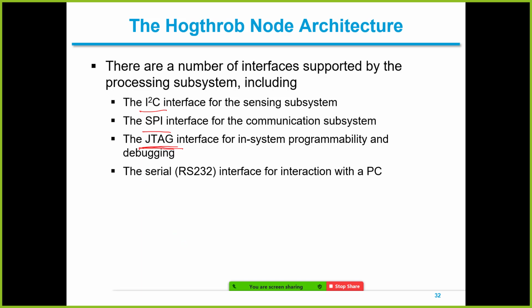So we achieve that through this JTAG interface, for programming and debugging. And the serial RS-232 interface is for interaction with the PC, through the serial port.